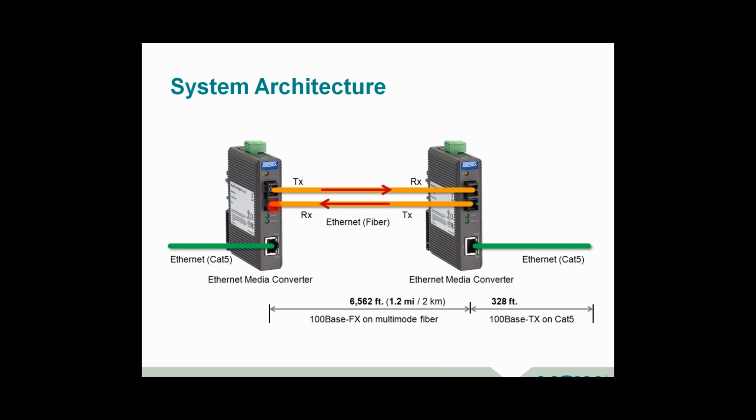There are other technologies to carry full duplex, meaning simultaneous transmit and receive over a single fiber, but doing so requires more complex, higher performance, and therefore more expensive optical transceivers utilizing a technology called wavelength division multiplexing. So that is possible, but if we do the 80-20 rule here, maybe it's closer to 90-10, most applications are going to utilize two fibers for a system like this, one for transmit, one for receive. Okay, so very simple to utilize in various applications.